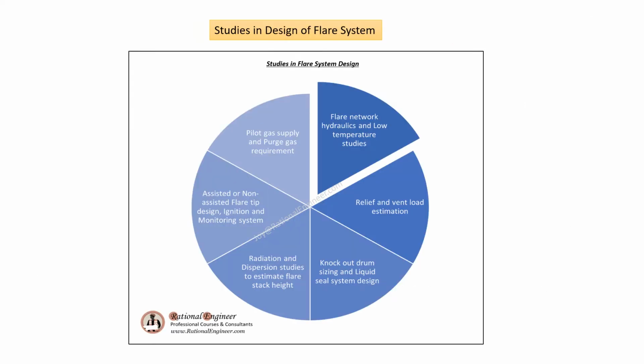The design of a flare system may involve different studies such as flare network hydraulics and low temperature study, relief and vent load estimation, which is an input for the flare studies, and sizing of knockout drum and liquid seal systems,